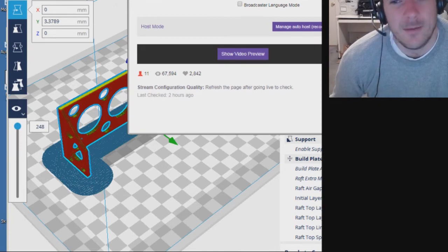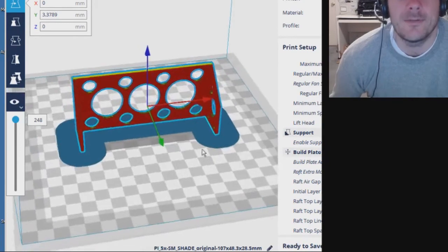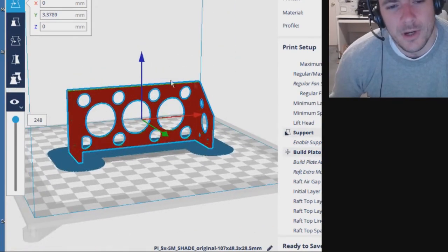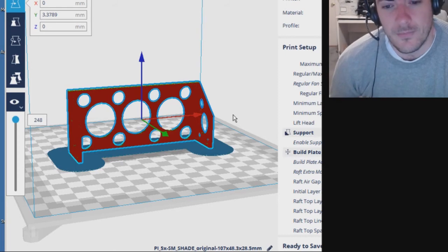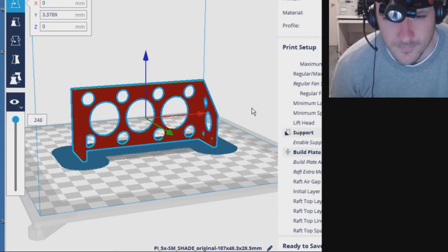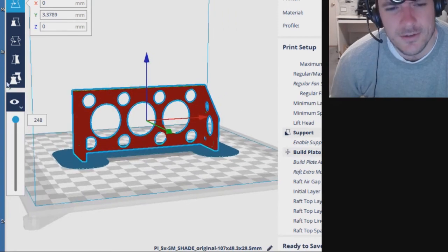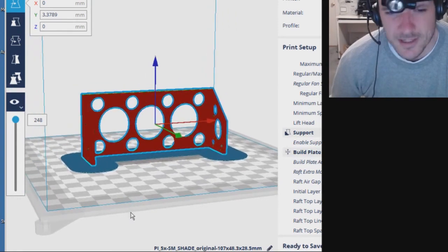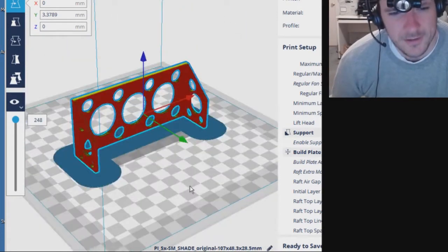No, I'm not going to give them a hole-filled mess, because I'm going to print out all the plugs for these holes. If I don't print them, then I'm going to put a sheet of masking tape on the back and pour in molten ABS to fill the holes. Kind of like filling dents on a car with Bondo. Structurally, it will be the same. You won't even be able to see them. I'm going to sand it all to a fine surface finish at the end. You won't even see a seam. It'll be seamless. They'll never know I did it. Meanwhile, the print will be perfect.